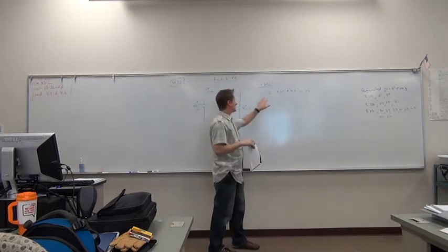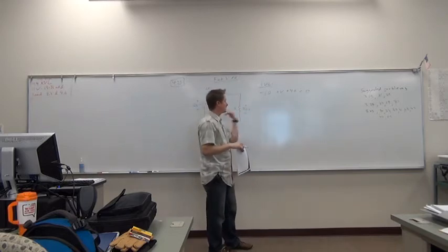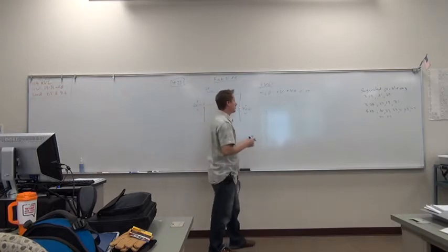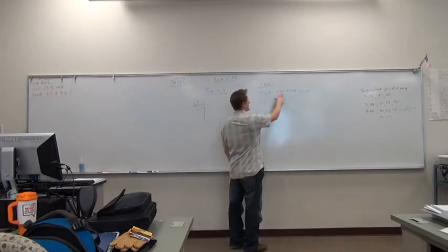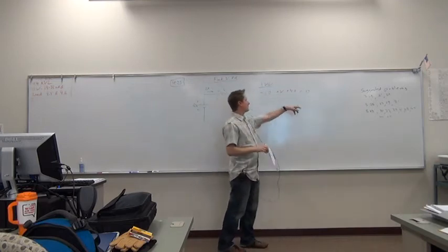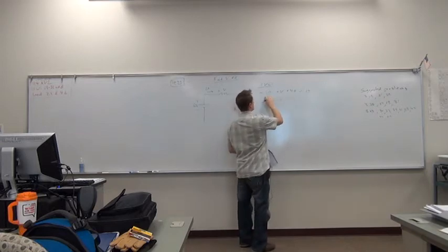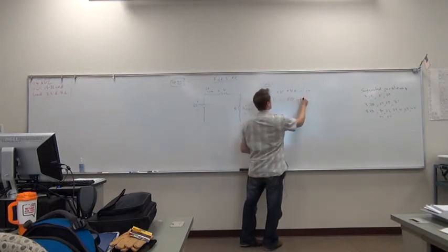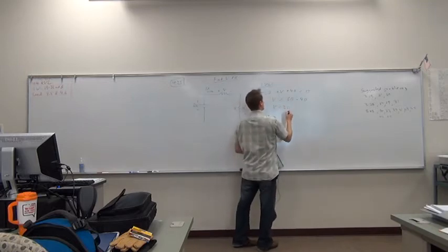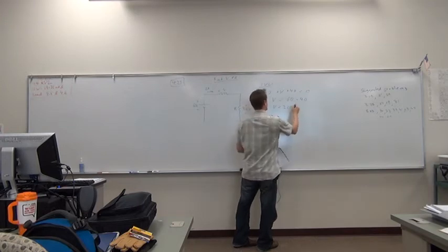In this case, you only have one unknown variable. Everything else is known. So you can rearrange the equation and solve for the unknown variable. So in that case, we can leave the V over here. We can move everything else to the other side. When we move everything else to the other side, the sign has to change. So you wind up with V equals 60 minus 40. V equals 20, right? 20 volts.